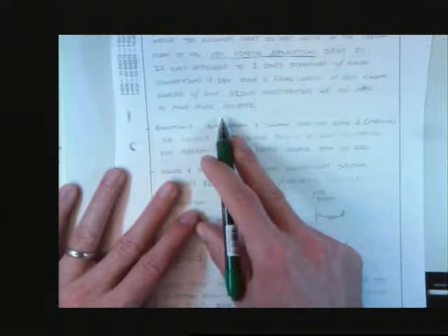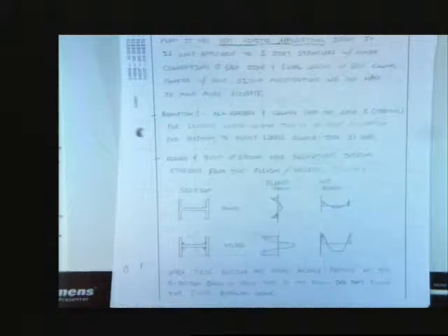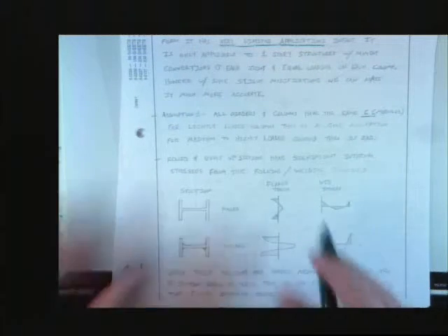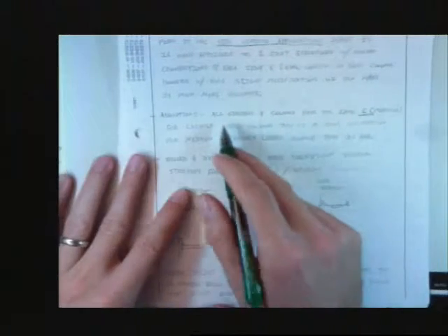However, with some slight modifications, we can make it way more accurate, and that's the magic we're going to be working in this class. We're going to talk about assumption number 1. All girders and columns have the same modulus. And I bet at the beginning of the class, or if you haven't seen something like this, you just said, "Chad, that's a great assumption. All modulus, what's the modulus of steel? 29,000 KSI, right?" Oh, you're wrong in certain circumstances.